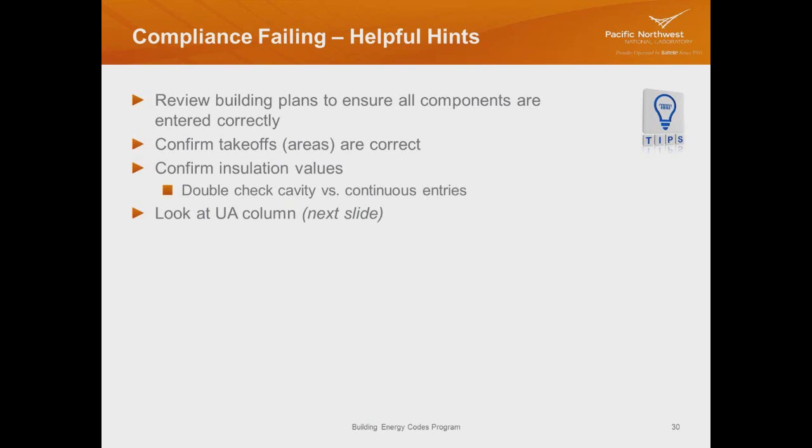But keep in mind, the code is not driven by the amount of windows you have any longer. So stringency is not increased, or energy efficiency is, you're not penalized for having a lot of glass. It does like for like components. So if you have a lot of windows, as long as they have a really good U factor, the more square footage you have of that component and the better it is than the minimum code, you're going to get trade-off for that component. You can use that for making up on a different component somewhere else. So it's really based on square footage.